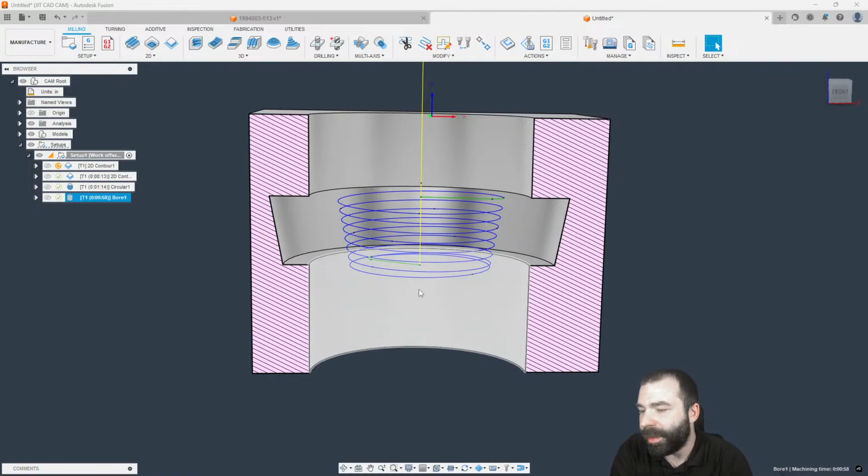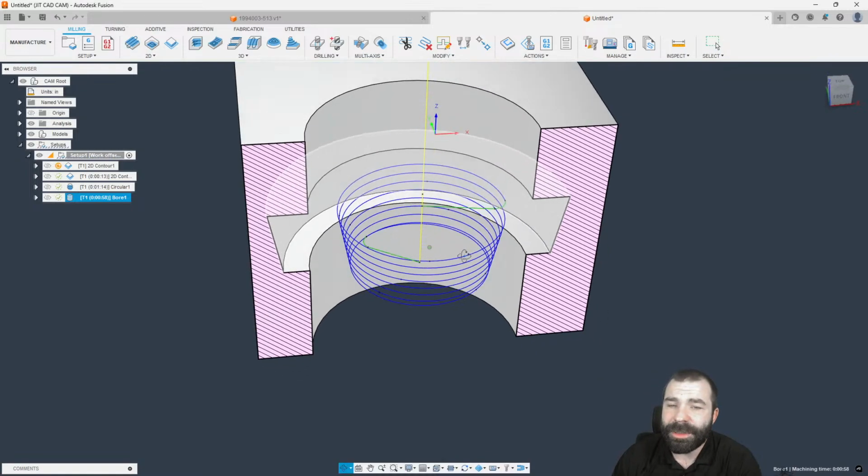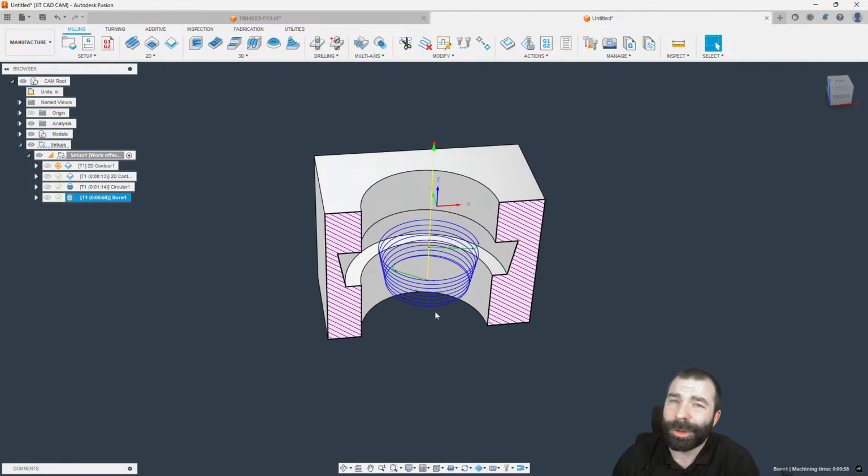But that would be another way you could draw, extrude, or actually revolve, and then machine down a taper bore as if you're doing it in a CNC mill. Keep in mind when you guys post this out, you could post this with polar milling too if you had a C-axis. Completely doable. So let's go ahead and jump back and move over to the other part.